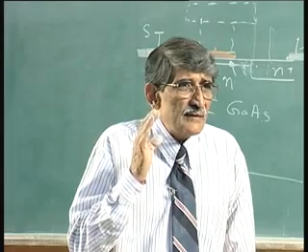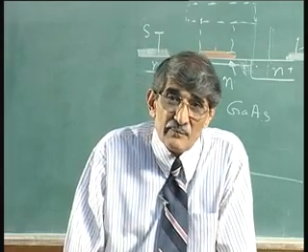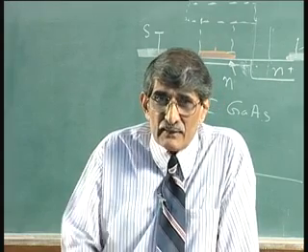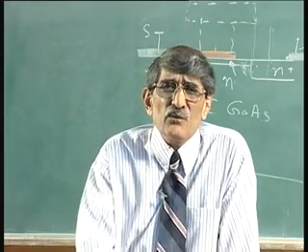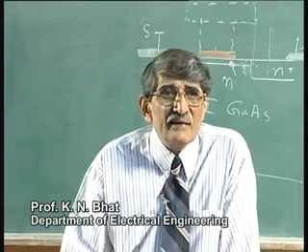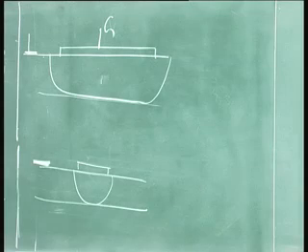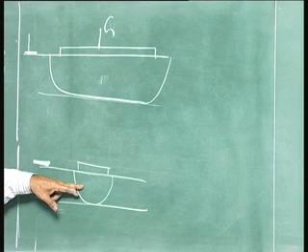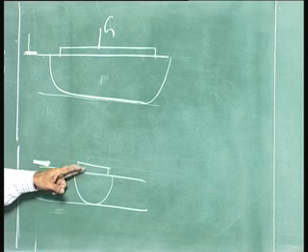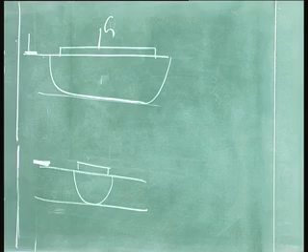So, what we are telling now is you can have the benefit of better performance by increasing the doping in the channel, and also reducing the thickness. You can't keep on reducing thickness, but you can increase the doping at least to 5 times 10 to the 17, but you can't go beyond that. What happens if I go beyond the doping of 5 times 10 to the 17, or 10 to the 18 maximum maybe? This will become ohmic. It will no longer be acting as a rectifying contact. There is an upper limit to the doping concentration that you can go.